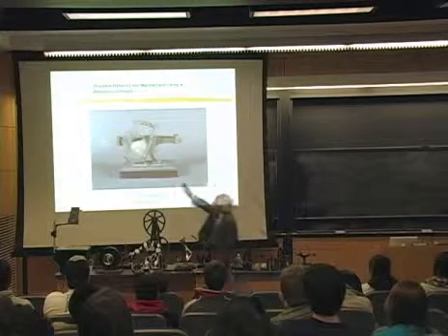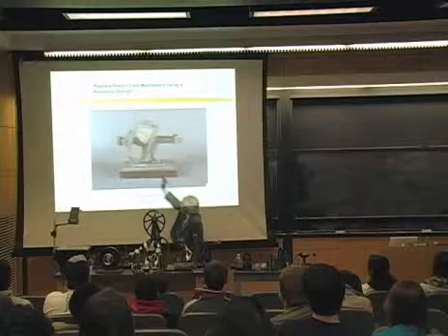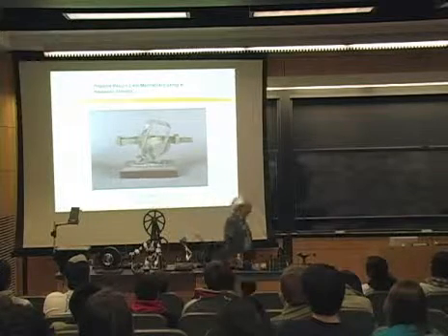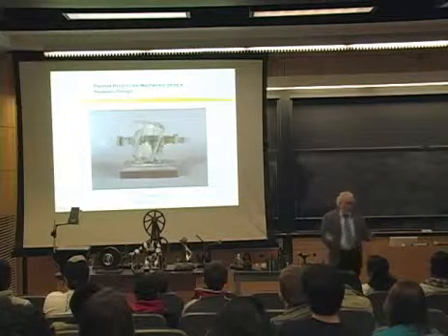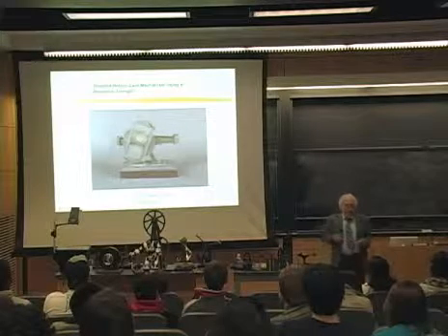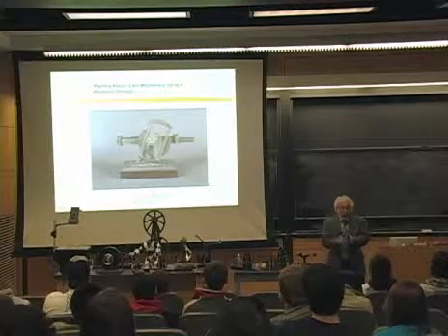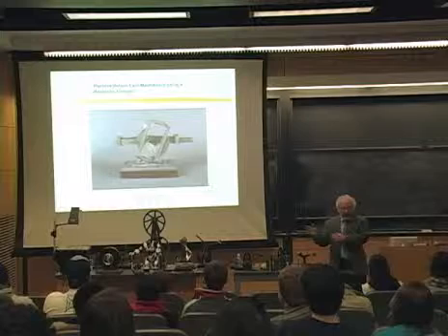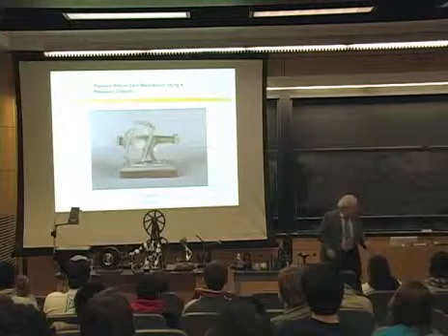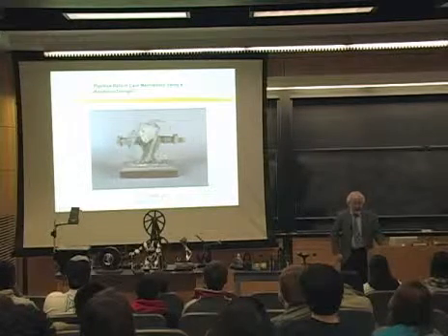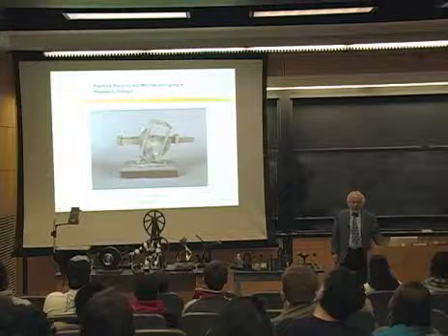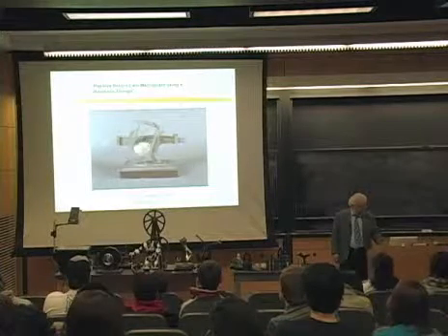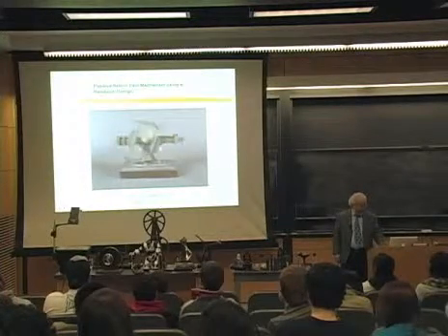In other words, at this end here it's pausing, at that end there it's pausing. And where would you use that pause? You might use that pause in a manufacturing operation. During the pause, you may want to drill something or paint something and then have the thing move on. So you can do things like have almost digital-like behavior with these kinematic elements.